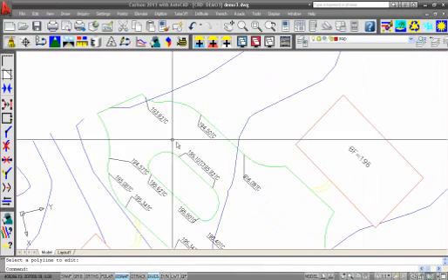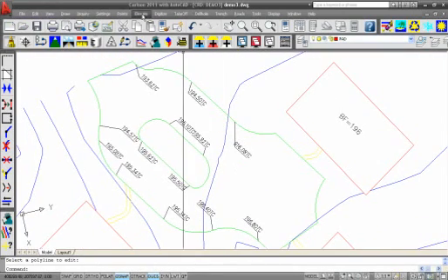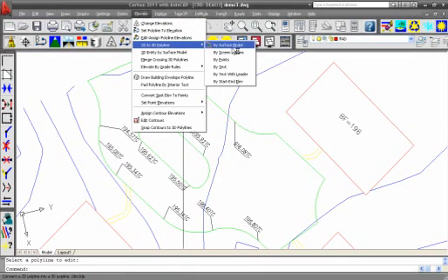We also want to use these labels on here. In older versions of the software, if I were to run by text with leader now, it would override our elevations that we just set by the contour line. Now, with 2011, this will add the elevations to that existing line, and they'll be locked in that other command. They'll be control points.